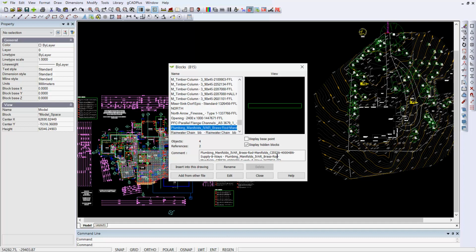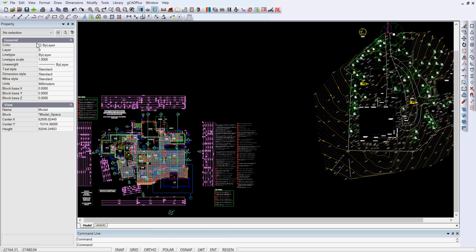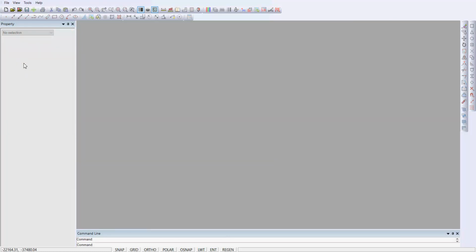And as I hope to show you in a little while, let's ignore that for the moment, if we save this drawing, remember it's called Test, and then close it, and then open it again, we get a warning, could not load the file. So some detective work has discovered that it's this application, which was developed in AutoCAD or an AutoCAD clone, has used incredibly long block names in the file. And as I'll try and show you in a moment, that's what's causing this could not load. We've got a corrupt file because the data that we started with was corrupt.